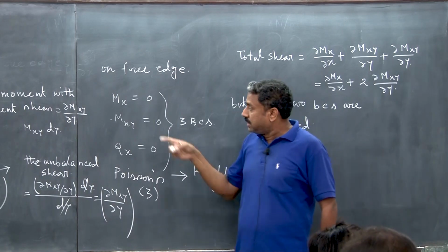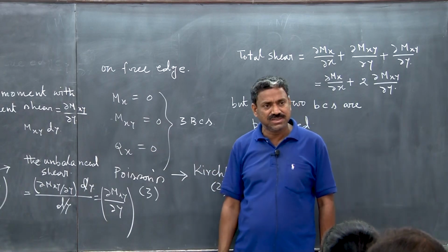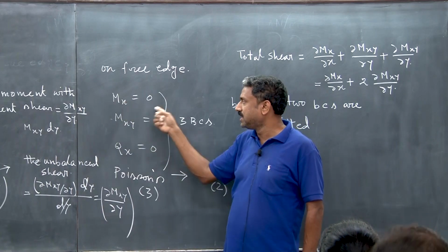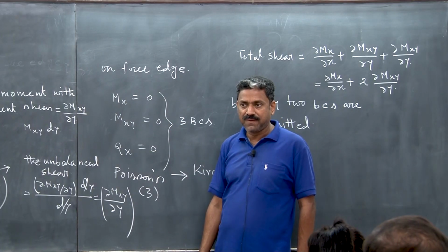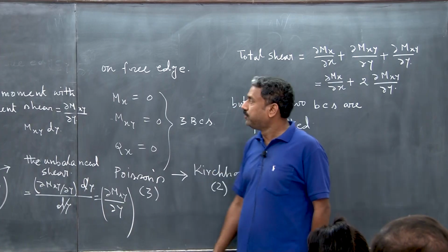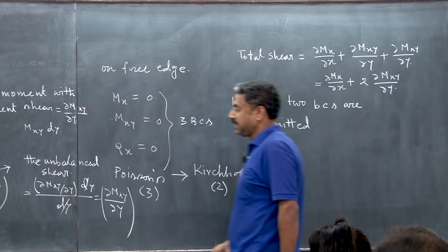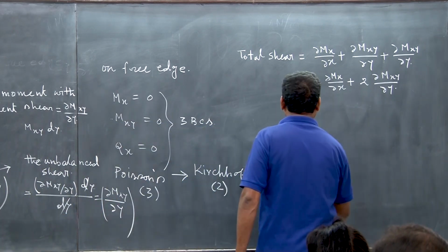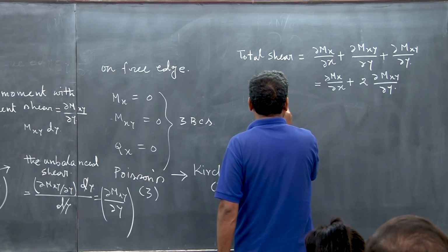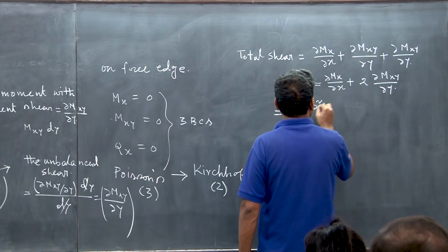So, now these two we can combine. So, from 3 the boundary conditions, Mx is an independent boundary condition and these two are combining into one. So, this shear is called Kirchhoff shear, okay. And then we can simplify it by substitution, so you just substitute, so it is minus D, d2w dx2.